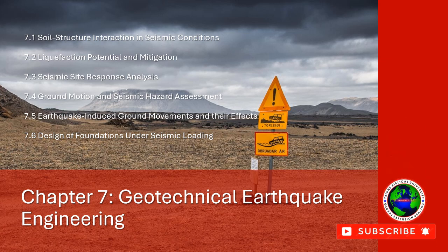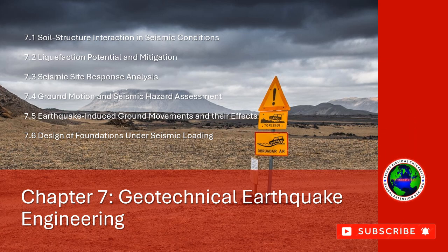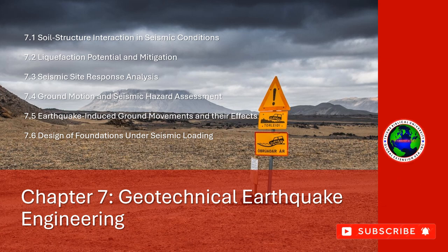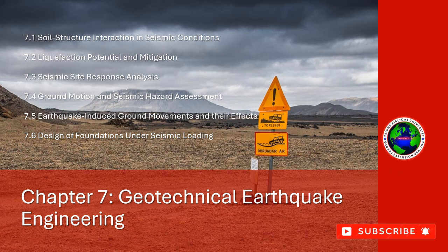5. Base isolation. Seismic base isolation. Base isolation involves placing flexible bearings or isolators between the foundation and superstructure, allowing the structure to move independently of the ground motion. This can mitigate the effects of liquefaction by allowing the structure to avoid or reduce the forces generated by ground shaking.